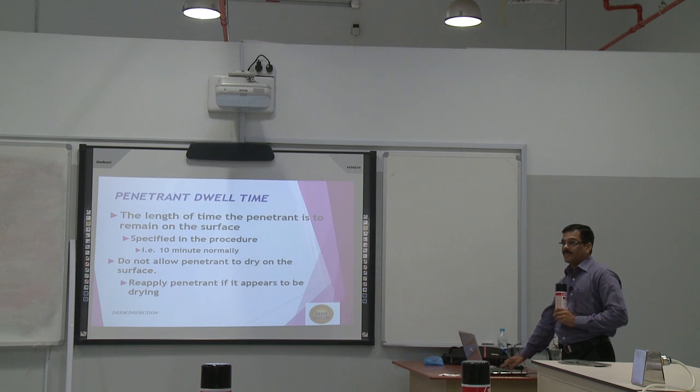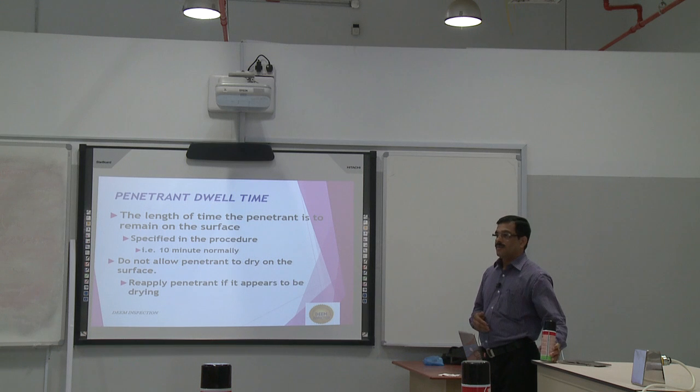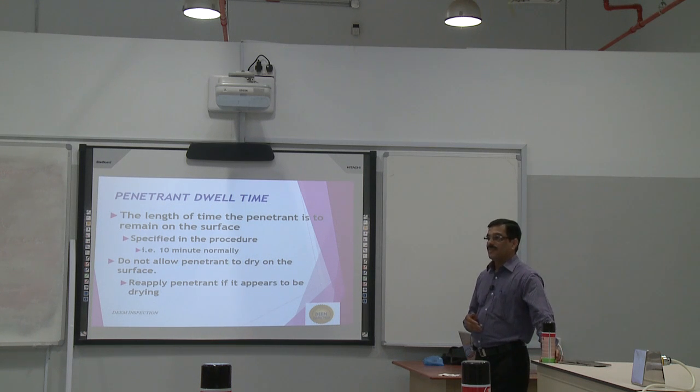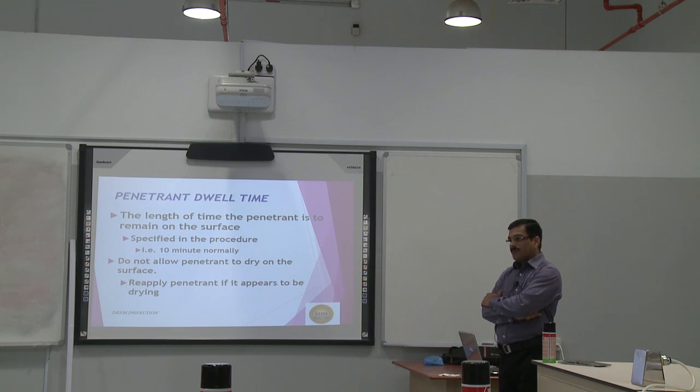Actually, we saw some application where they were using that technique. First they applied one coat, then gave it more than double the time. After that they let it dry, then cleaned the surface again and reapplied, then gave the normal double time. After that, apply the cleaning and then the developer and read. Actually, that was in the SOP.